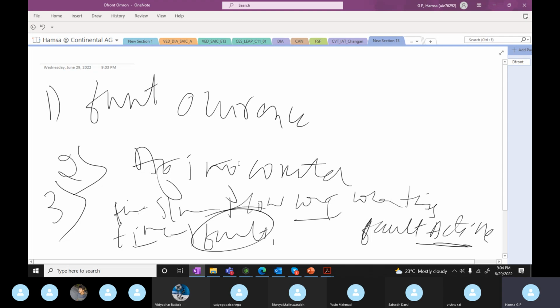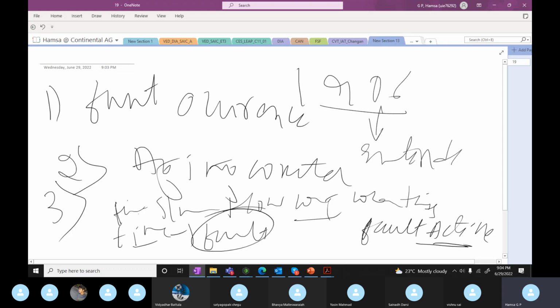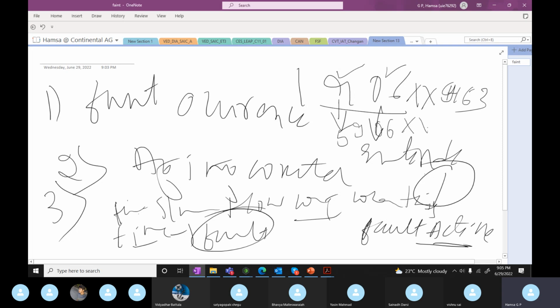So when it comes to 1906, it will provide the extended information about one particular fault. The request will be 1906 and then the fault DTC number, which could be 9163 as we discussed. If the ECU is responding positively, 5906, and I will come back to this XX later. This is called the status byte. I will come back to this.